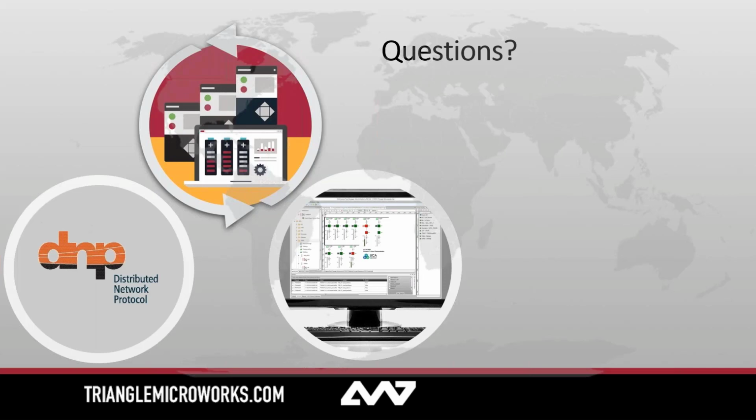Okay. Next question, and you kind of touched on the time sync a little bit already. Can we conduct FAT testing using DTM, and how about time synchronization in DTM testing? So if you're going to do a time sync, what you need to do, I think, and Dave can correct me if I'm wrong, is have whatever machine is simulating your devices sync up to whatever is the controlling time sync out in the network.